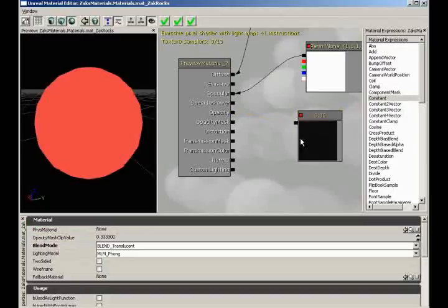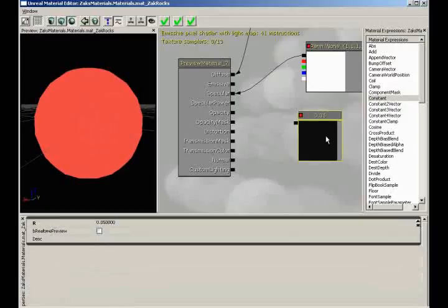Now, I'm not going to go into how to do that. That's a little bit advanced for this video series, but I will point you in the right direction. You'd be doing that with either a cube map of some lighting, and in general, in your level, if it is a static object, light maps that are generated when you build lighting will show up. So all that to say, if you have a translucent object that is static, it will still have some sort of lighting on it if it's not moving at all. Remember, the key word there is static. If it is a dynamic object, it's going to end up looking like this, where it's kind of flat and loses its lighting. So food for thought for later on down the road.